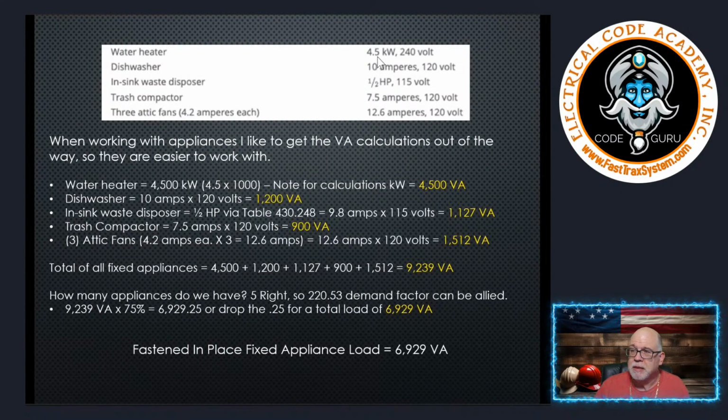We're not talking about a gas hot water heater that has a blower. That would typically be just a 15 amp branch circuit to a receptacle. It doesn't typically even have to be dedicated. It might be one of those receptacles down there for the 3 VA per square foot, just a general use receptacle you plug into. You've got to look at the instructions from the manufacturer to see whether they call out something dedicated or not.